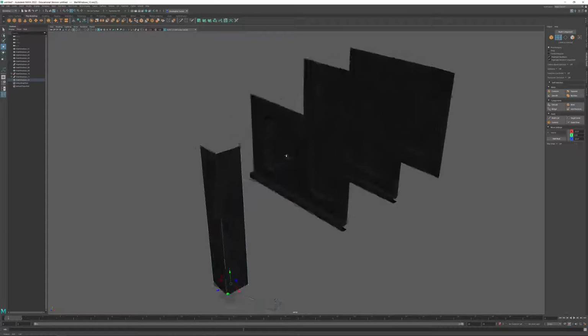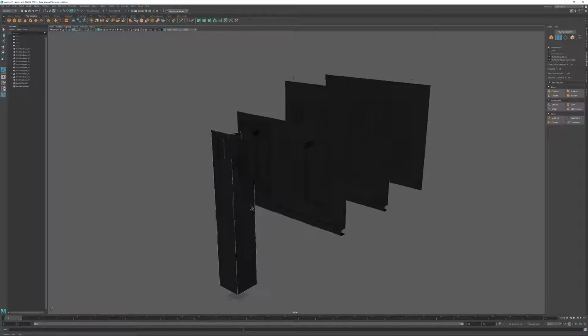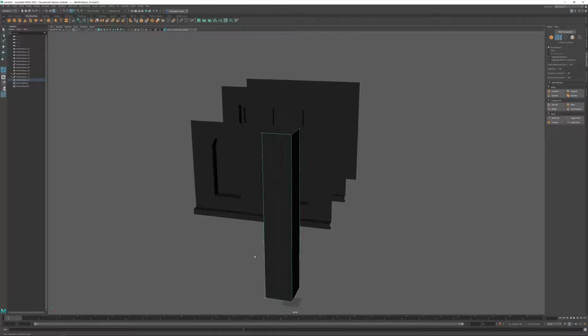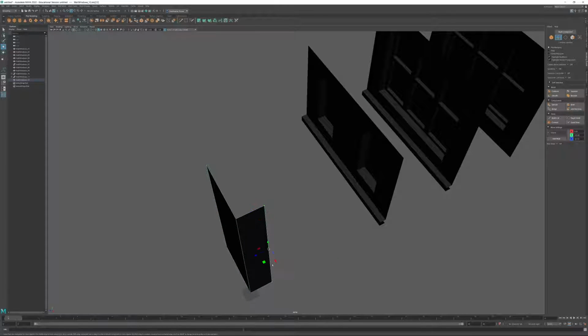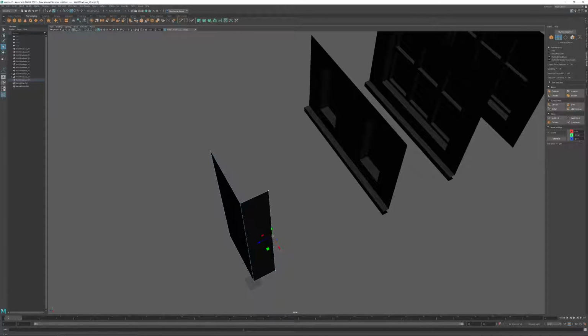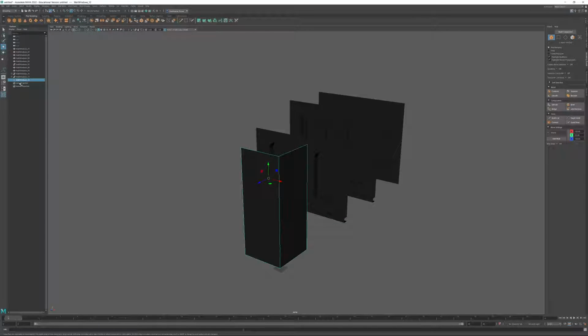It's not the right dimensions yet, though. That's easy enough to do. Let's also make sure that Edit Mesh, Merge, is done. So we have 6 vertices, 3 atop, 3 below. And I'll grab these 2 vertices, and we need to move them in X. Right now, they find themselves at negative 41. I'm going to do negative 100. And then I'll grab these 2, which are going to move themselves in Z, and I'll put them at negative 100. I now have my first corner.